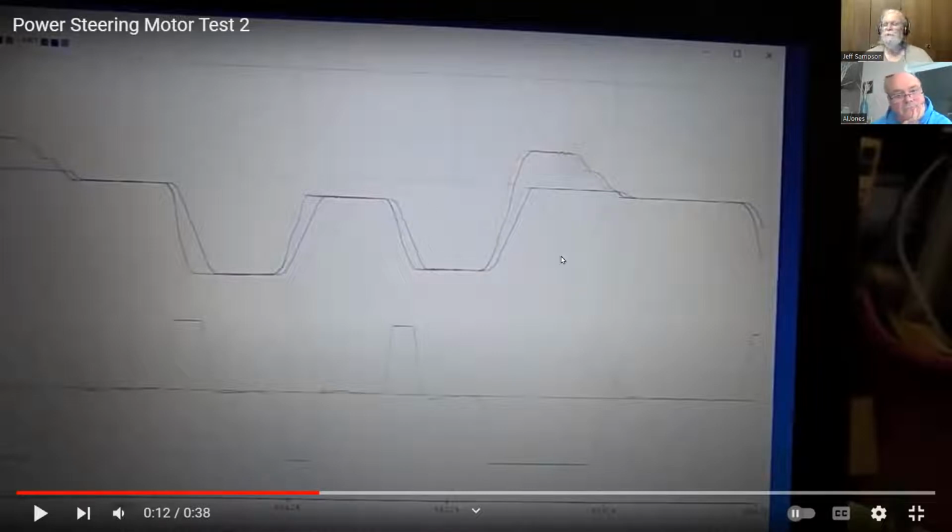So I think that's just something to add in that is going to protect things. I can go look up the code. It's on some Arduino IDE somewhere on one of my computers, but it's just a couple of lines of code. As I say, in your output routine, say if I'm beyond this point going left and the direction says go left, then just kill the motor power. In your case, just write steer effort to 0.